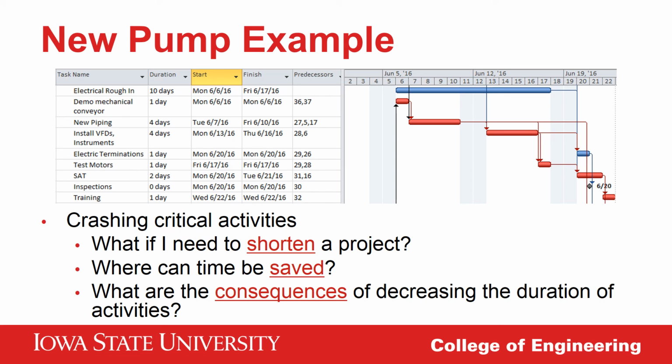So I can move demolition from June 6 to June 4, and the same for activities the following weekend. At this point, I've started production 4 days early and increased my costs around $20,000 for the weekend work. This increased cost is still less than the profit I expect to earn, so I can keep cutting.